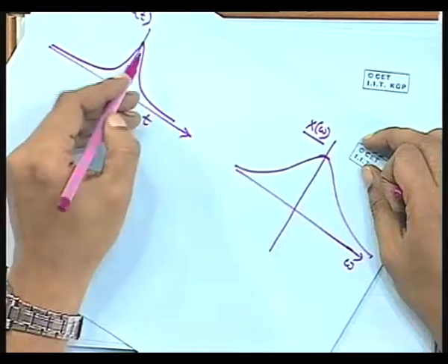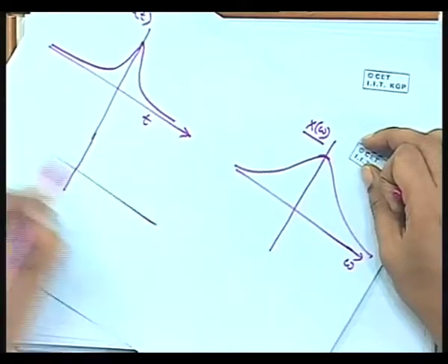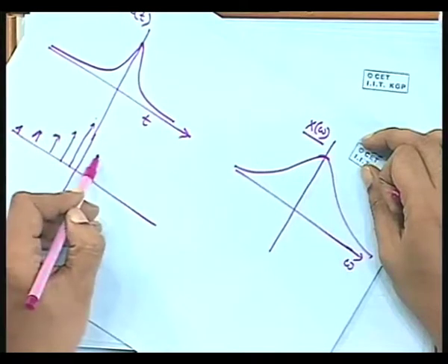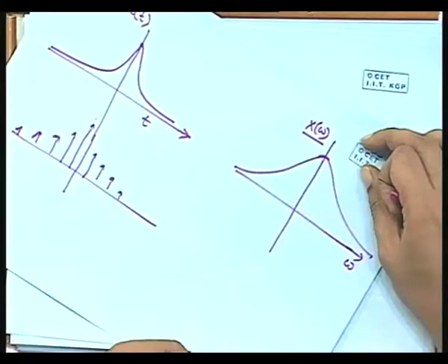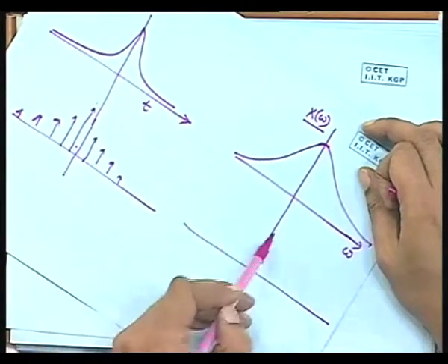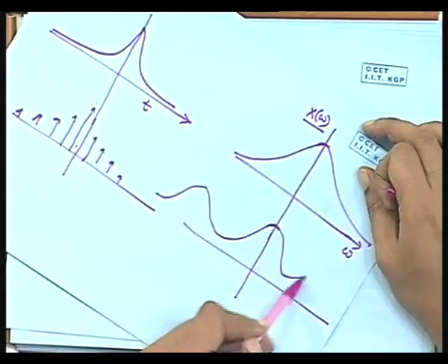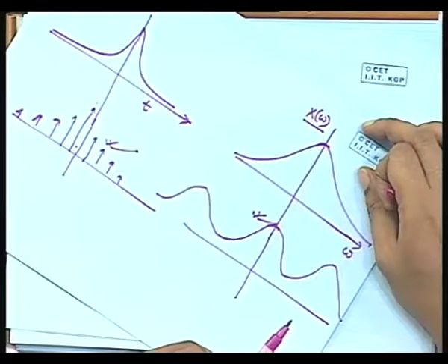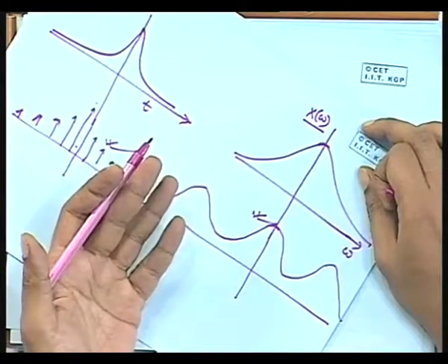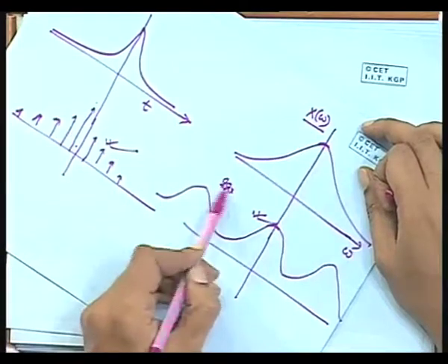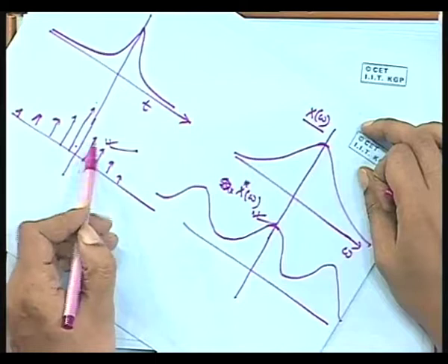Now what will happen if you sample this and get a sampled sequence, and then after sampling, if we take its Fourier transform? We know that X(omega) will now become periodic. So if we sample in the time domain, this will become periodic in the frequency domain, right? This is obvious because it will become a periodic function of omega. This is our Sxx(omega), I mean, this is actually X star(omega), where this is x star(t).